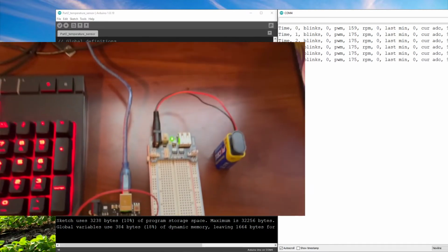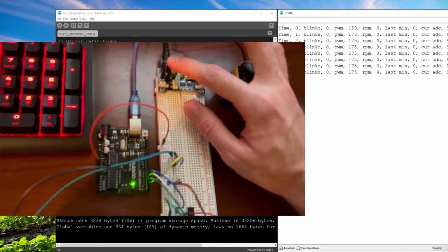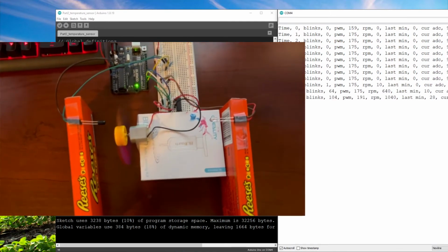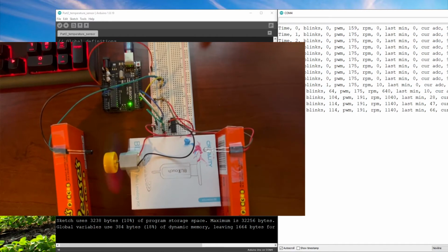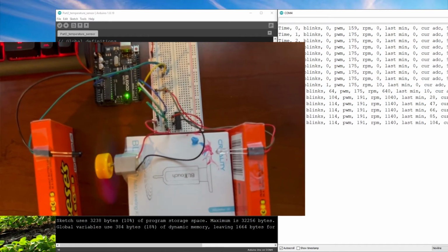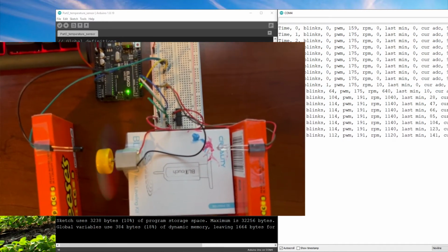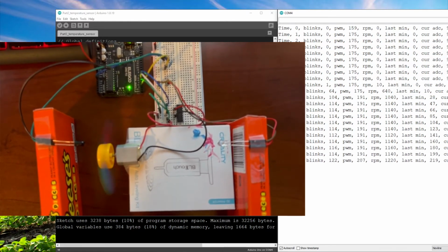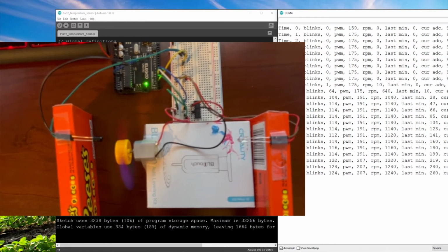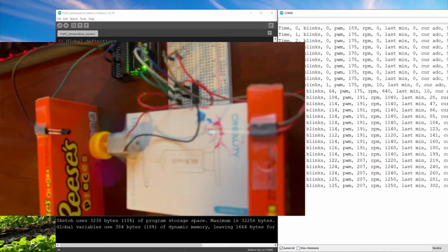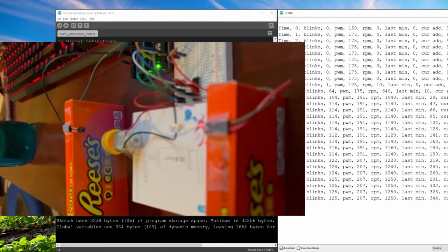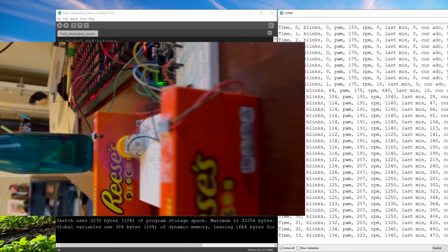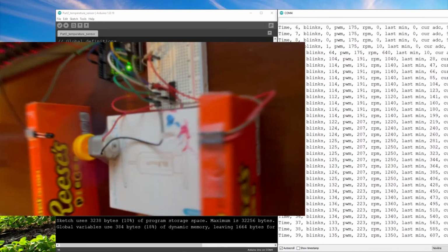We're recording 0 RPM, and now we start the fan, and we are seeing a lot more rotations. As mentioned in the code, the PWM started at 175. It missed a lot of that startup because there was no power being driven, but it increments by 16 every 10 seconds until it hits 255, the maximum. Then it will roll over back to 175, and we'll see an appropriate drop in the current RPMs